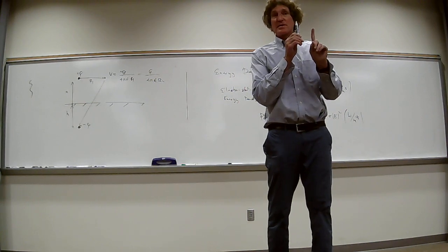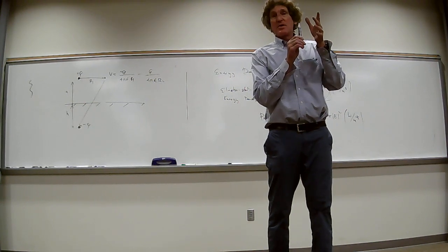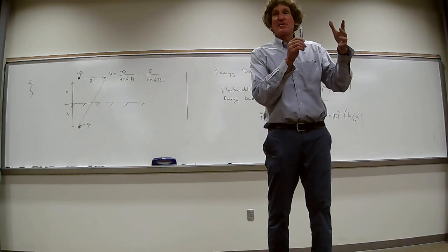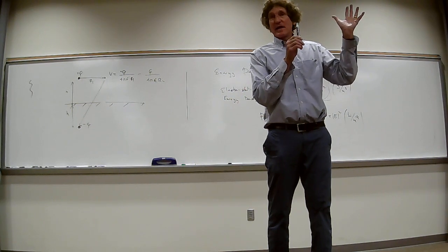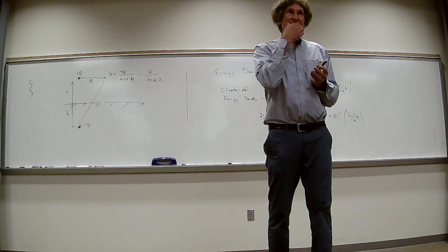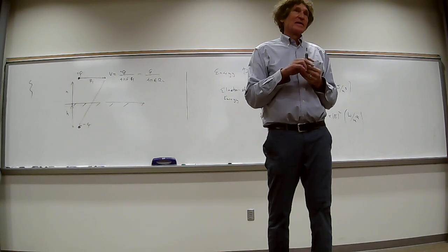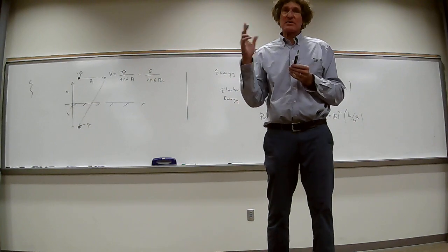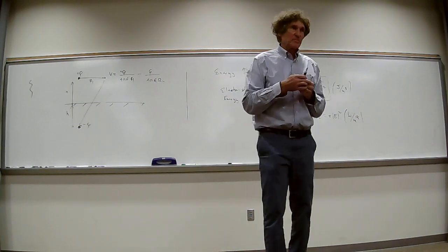And here's what happens. When you start approaching that limit, then all of a sudden you'll get this corona. You know what corona is? It's ionization. And you'll see arcing, and nothing will start radiating. It's the upper limit on what you can do. And I'm going to tell you, I've never dealt with really super high power stuff like that. But I know it is a problem that I'm very aware of. Just be aware of that.